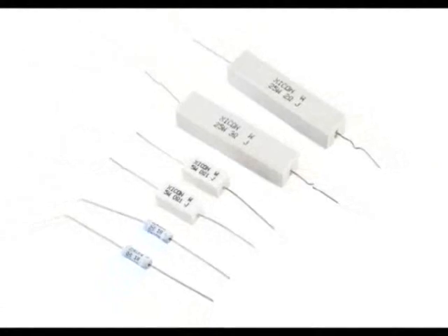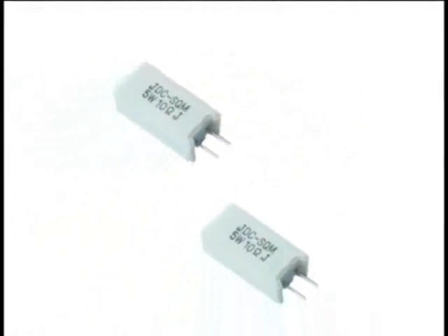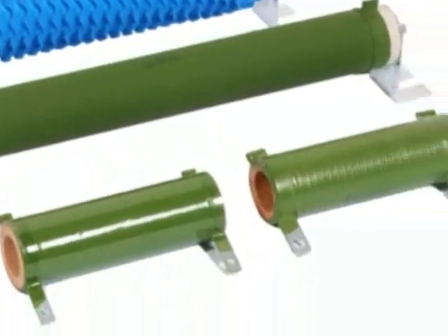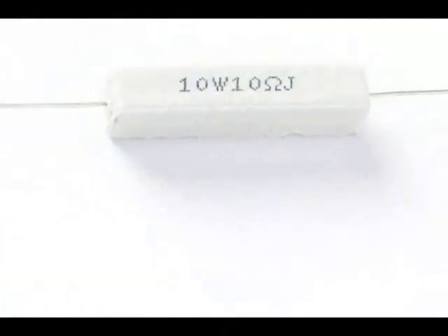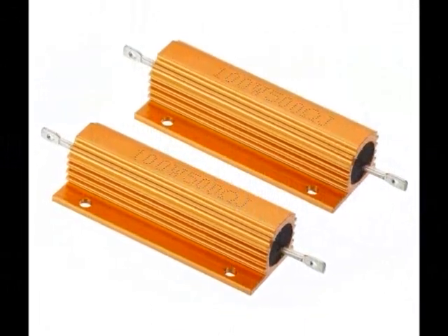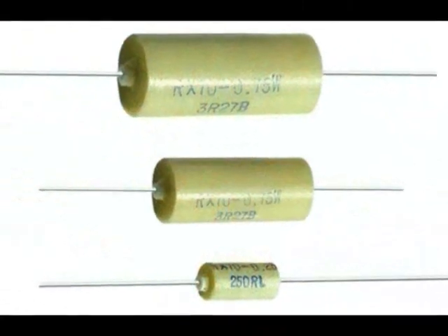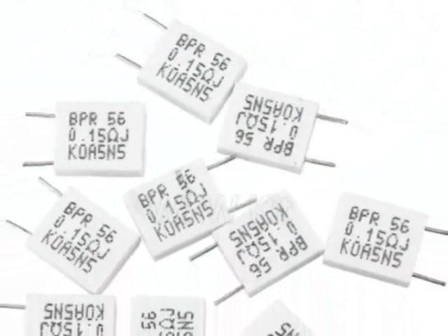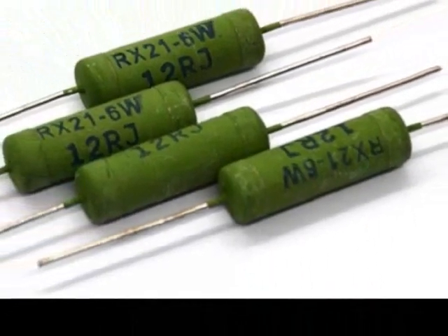Brick resistance is also one of the types of fixed resistance that is placed inside the ceramic cover to withstand high powers and is filled with a special type of insulation under these ceramic covers. These resistors are available in the market from 1 watt to dozens of watts. The important thing about brick resistors is that they may get very hot during operation, and a suitable place for their installation should be considered in the circuit design.